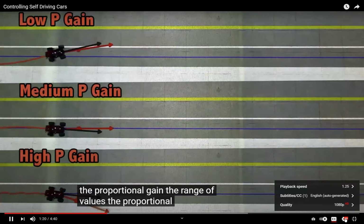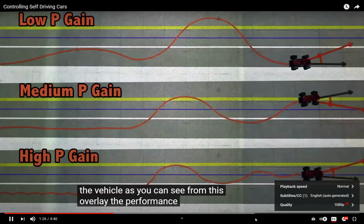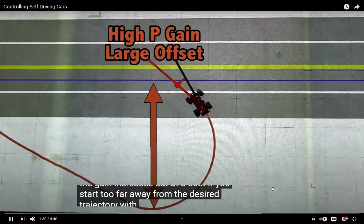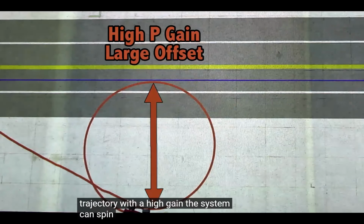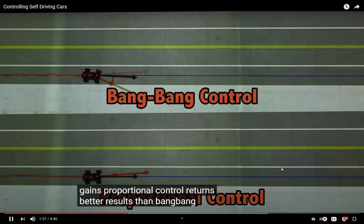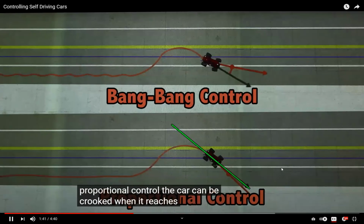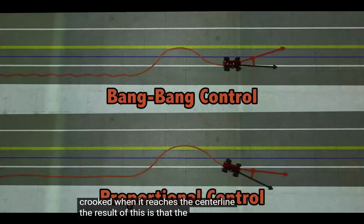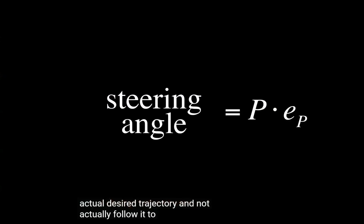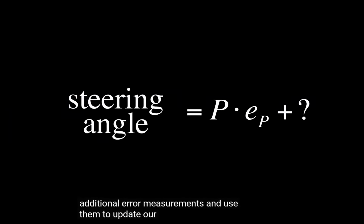The range of values the proportional gain can take drastically alters the performance of the vehicle. As you can see from this overlay, the performance gets better as the gain increases, but at a cost. If you start too far away from the desired trajectory with a high gain, the system can spin out of control. With the best gains, proportional control returns better results than bang-bang control, but it still doesn't work that well. With proportional control, the car can be crooked when it reaches the center line. The result of this is that the controller will repeatedly overshoot the actual desired trajectory and not actually follow it. To correct this overshooting problem, we need to consider additional error measurements and use them to update our steering command.